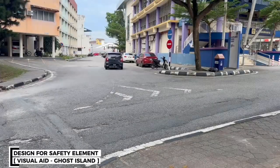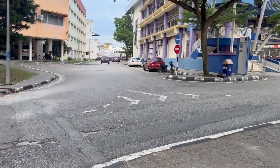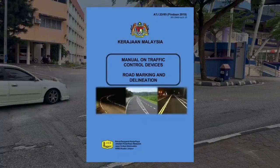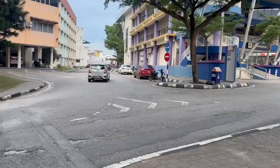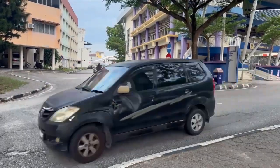The next mitigation measure is the use of visual aids, specifically a ghost island, which is designed following Arahan Teknik Jalan. However, at the study site, the existing ghost island is not clearly marked and lacks proper visibility, which may confuse drivers and reduce its effectiveness.